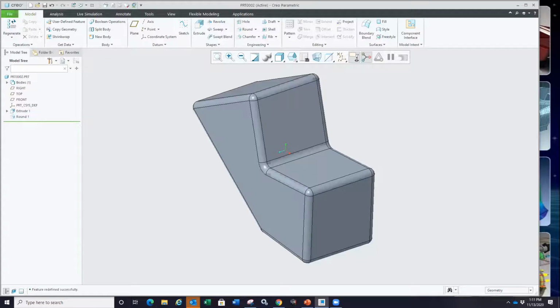And let's see, is it possible to add datum references to extracted bodies in the auto-generated external copy geom? Yeah, when you do an external copy geom, you are able to select datums, right? You're able to include datums, curves, and you're talking about the extracted body, like I showed you in that. Yeah, you should, because you're still allowed to select planes and axes, and as long as that body is in the main body, which it is, you should be able to select it.